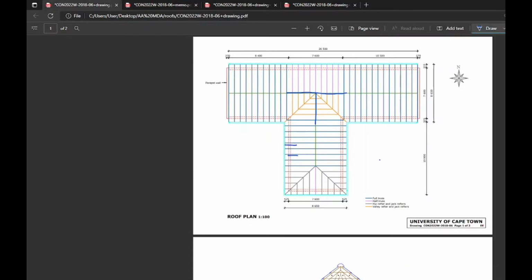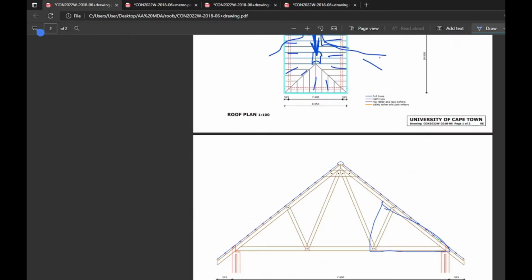All these tiles, they're lapped nicely so that they are nicely waterproofed. Water comes and runs down, it hits here, it runs down, hits here, it runs down. But if it hits the center and we haven't placed anything, it is going to enter the roof. So what a ridge tile is, is basically a little cap to ensure that if water happens to land in the center, and we can assume that because it's rain, it will land in the center and won't decide not to, it's going to hit the ridge tile, run off, and because all the tiles are lapped nicely, bounce, run down, bounce, run down.